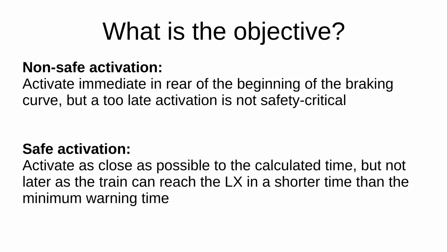LCPS so that the level crossing protected message reaches the train immediately before the train reaches the braking application point, so that neither the LCPS is activated for longer than necessary, nor the train must brake because of the braking curve. At level crossings with safe activation, it must be ensured that the command activate is never given too late. This implies that the time of activation must be calculated safely depending on the further movement of the train.